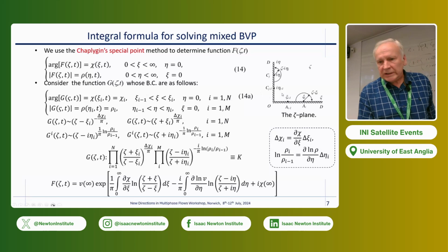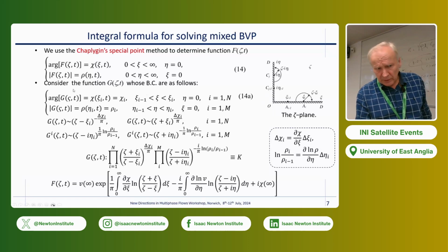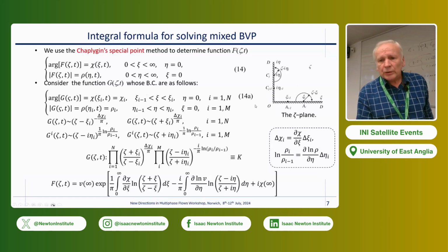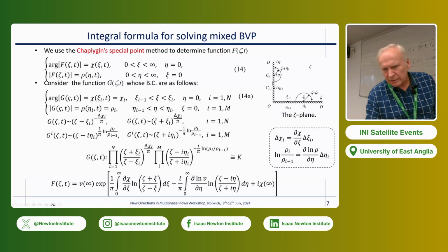and we need to extend it in such a way as to keep the magnitude of the velocity constant at the interval. So we need to put the additional singularity at symmetric points of inverse order. Then we need to extend the upper half plane to the lower half plane, and additional singularity appears at points symmetric to the points eta j.